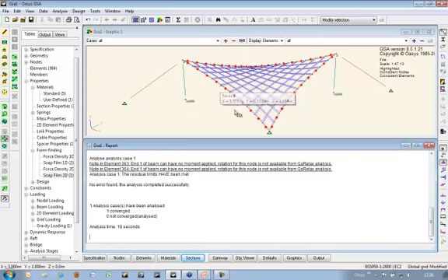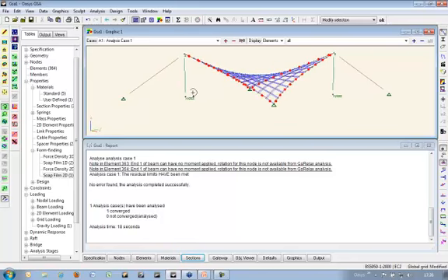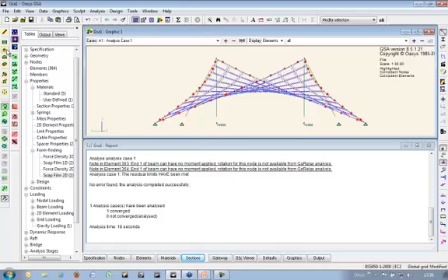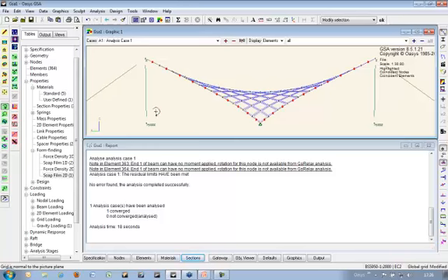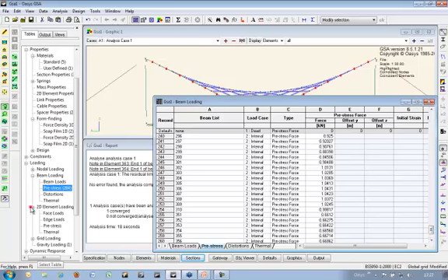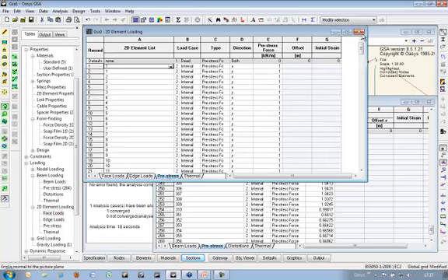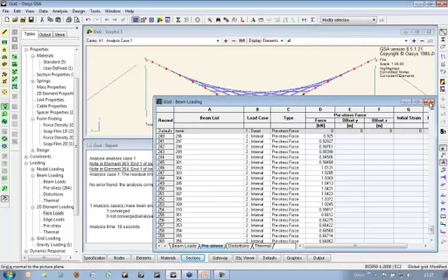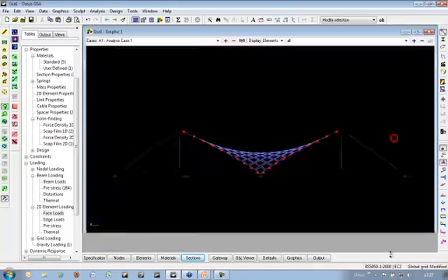So what we've now got is the found geometry, and you'll see that those columns have angled over a little bit, but they're still pretty straight. But we've also now got pre-stressed loads in the edge cables and pre-stress forces in the fabric as well. Right. If we're happy with this pre-stress, let's unshape.